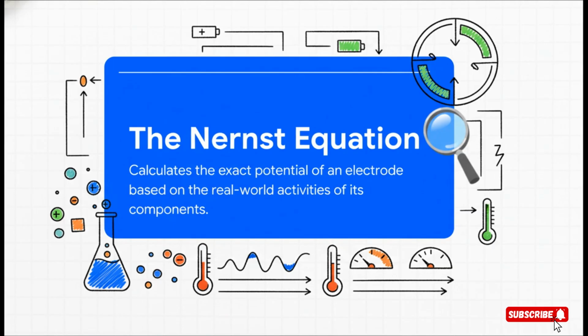Okay, so those galvanic series tables are awesome for a specific environment, like seawater. But what if your pipeline is buried in soil that has a totally different ion concentration? Or what if it's operating at a higher temperature? We need a way to adjust those standard lab values for real-world conditions. And that is the power of the Nernst equation.